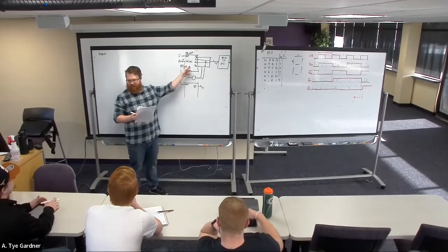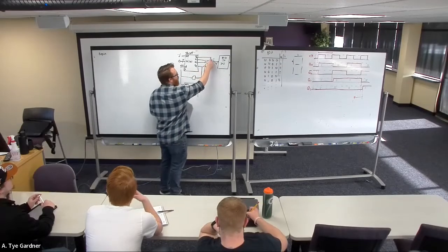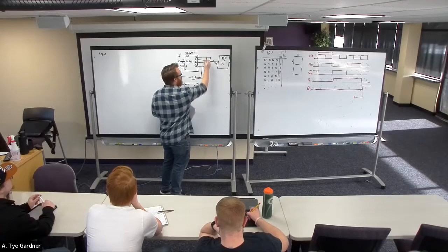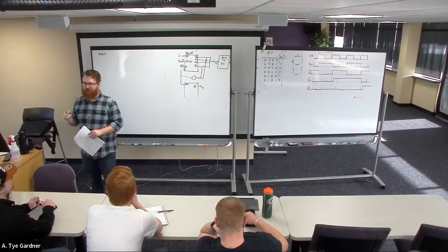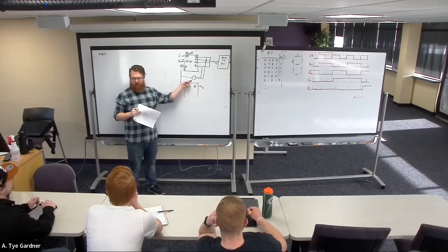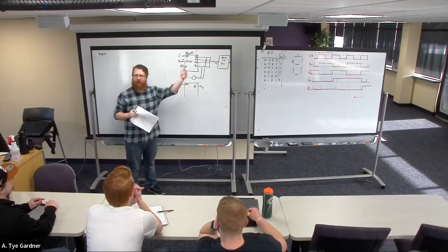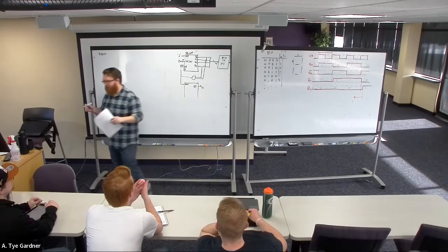Let's build this 4-bit counter with, let's plan on having it designed as the synchronous load. So this is going to load when we get to 9, but hopefully it doesn't do that until after it's had a full clock cycle of being 9. Right, we don't want it to skip past the 9. That's what we want to design.